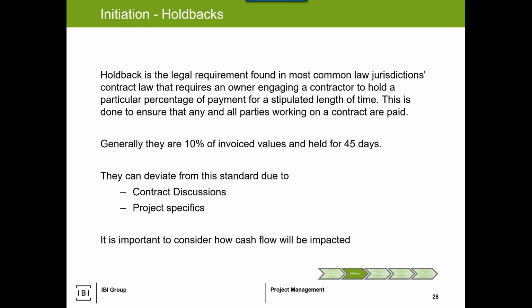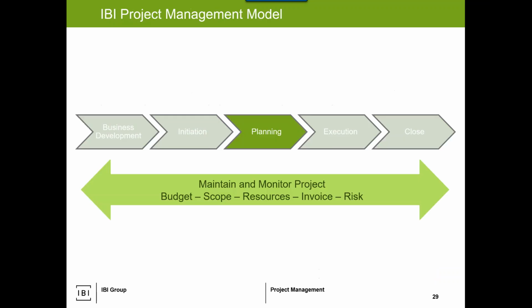Holdback, now again, because we're global students, I'm not exactly sure if this applies everywhere, but usually there's a 10% holdback that's done in Ontario and possibly in other jurisdictions around North America. Won't dwell on that, but it's kind of like a protection for those who are making the payments.